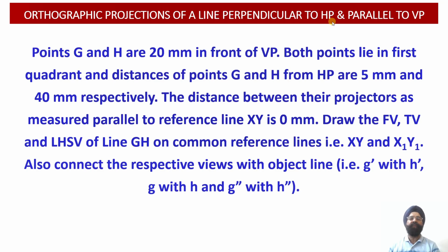And this line will also be parallel to the profile plane. So the profile view projections, that is the left hand side view projections of this particular line, will also be revealing the true length projections of the line onto the left hand side view projections. Now let us read out the statement of this problem.